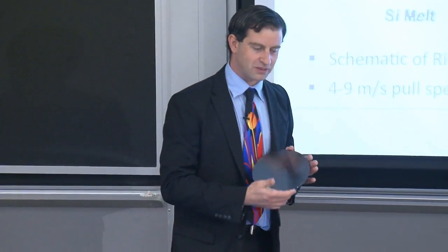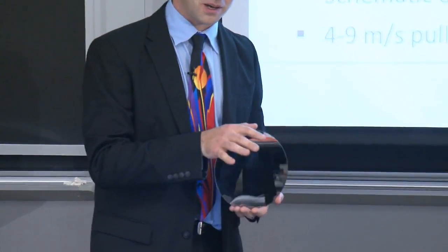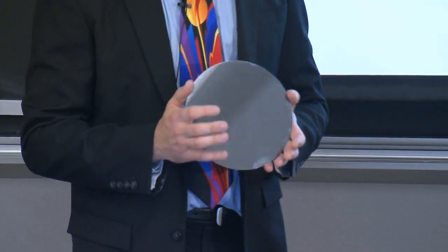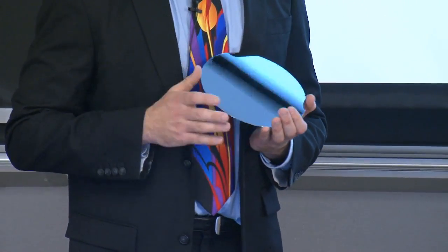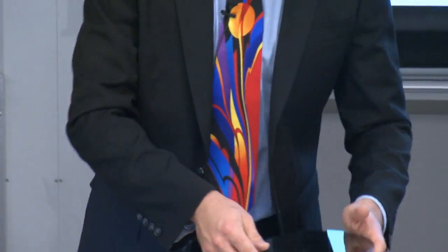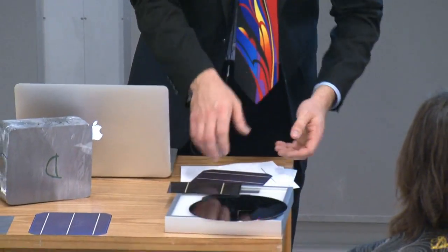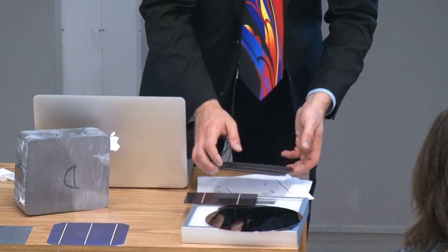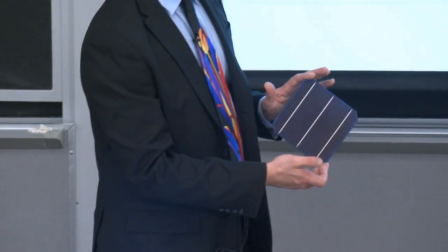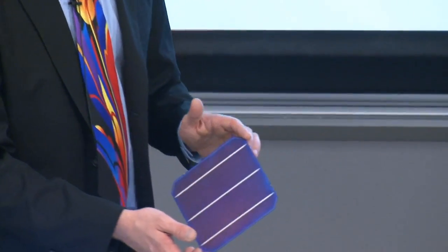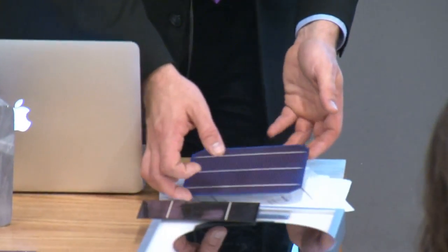And so the idea was to optimize between the cost of the silicon and the cost of the encapsulant materials by shaving away a little bit of the silicon and losing that, and perhaps recycling it, to be honest. And the encapsulant materials where you have this dead space in between the wafers, a small amount of it, where you have glass and encapsulant but no active device underneath.